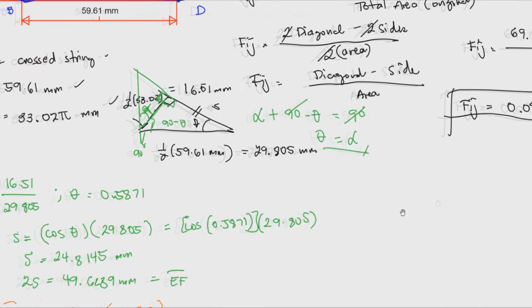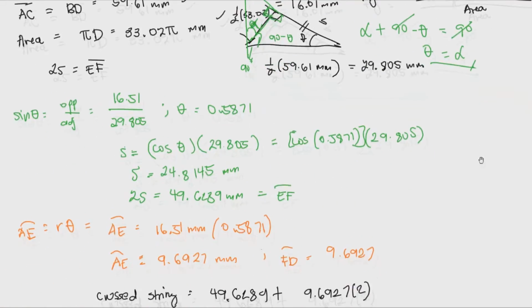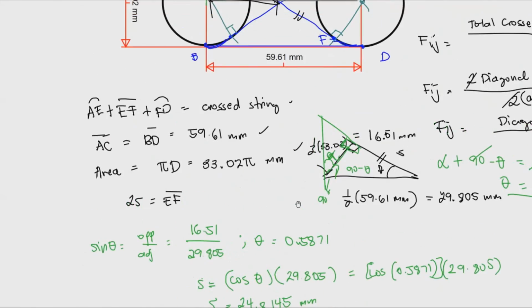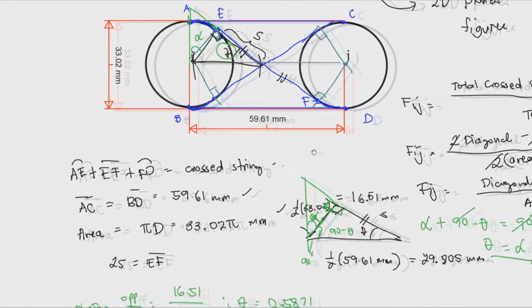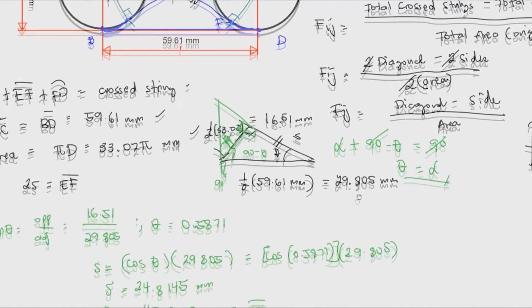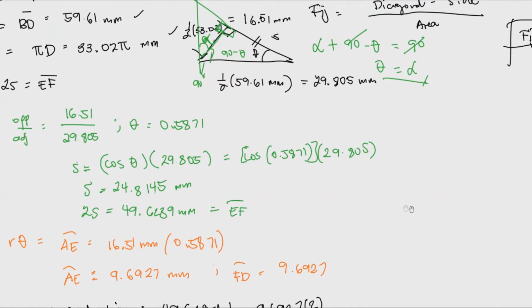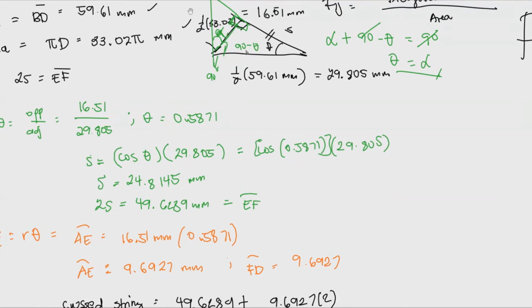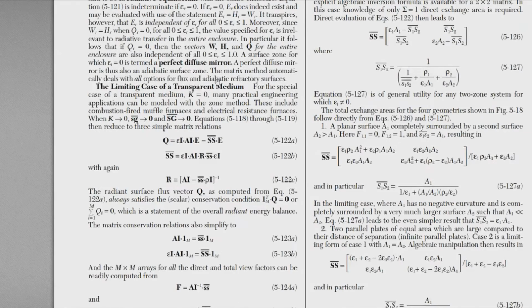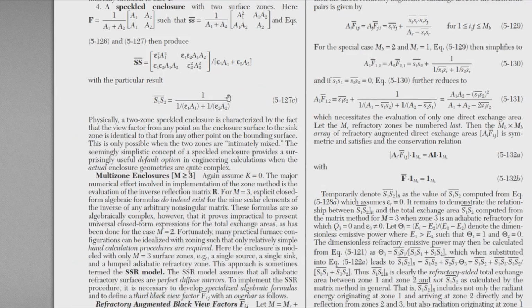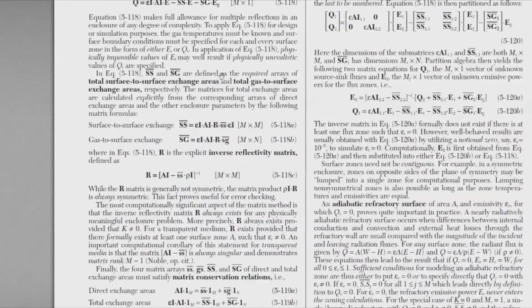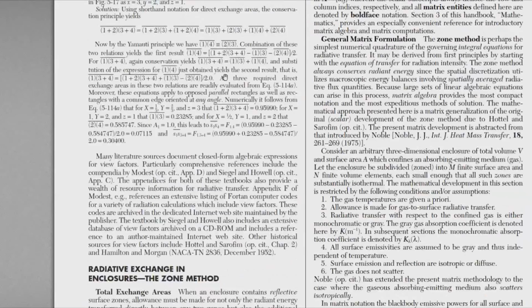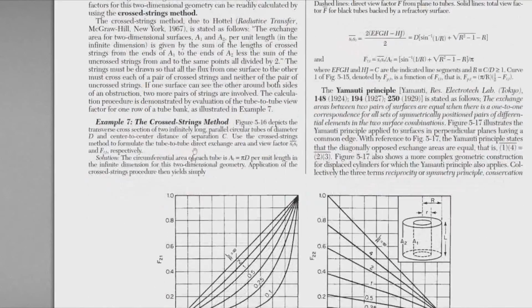So that is the view factor for this figure. That's 0.0966. So I hope you understood how this works for the derivation of the strings. It's kind of messy because there are a lot of figures and graphs. But in the Perry's handbook, you could see a simplified form of this cross string. So let's head over to this chapter, the cross string method.